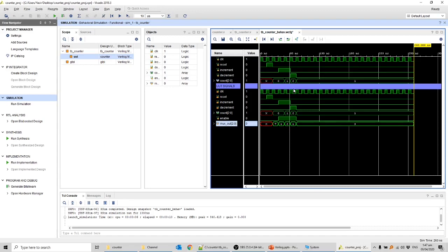If the design had not been working properly, let's say the counter was not incrementing, then I could have seen why it's not working. I could have seen whether the mux out value is correct or not, whether enable is correct or not. These are the signals that were actually input to the count register and the enable of the count register. So these values will give me a chance to backtrace, and that's the main reason we use simulations. So that's it. That's how we simulate in Vivado.